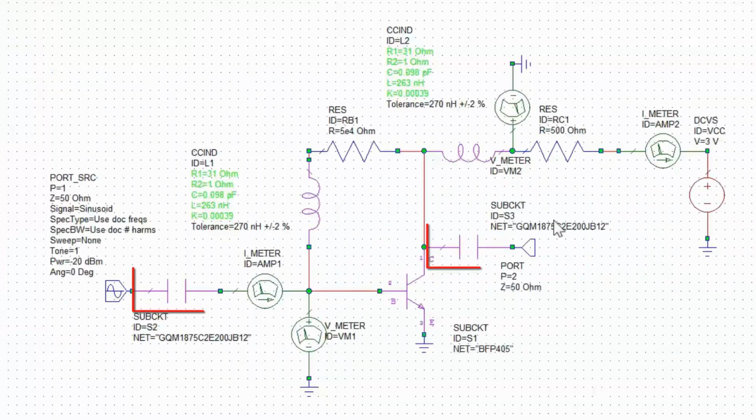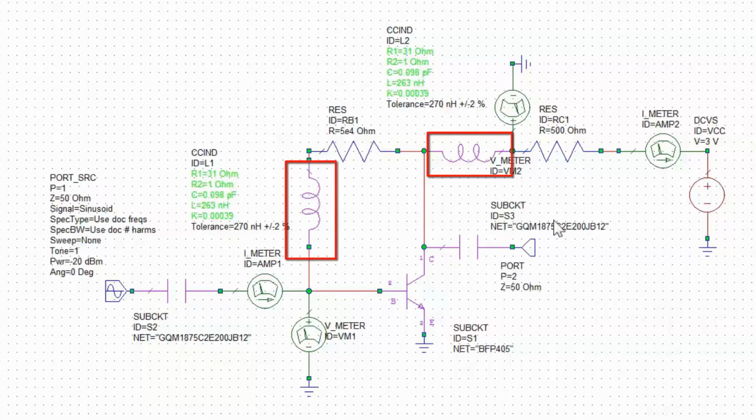So now we've got capacitors in place that avoid the DC bias network being loaded by the impedance of our RF sources. And also we've got RF chokes that prevent the RF signals from going back into my bias network and up to the power supply and modulating the bias voltages. So we are in a safe place to be able to measure the S parameters of these transistors. We've seen what S parameters are about. They obviously can measure the reflection coefficient, which is what we've used them for in the passive circuits.